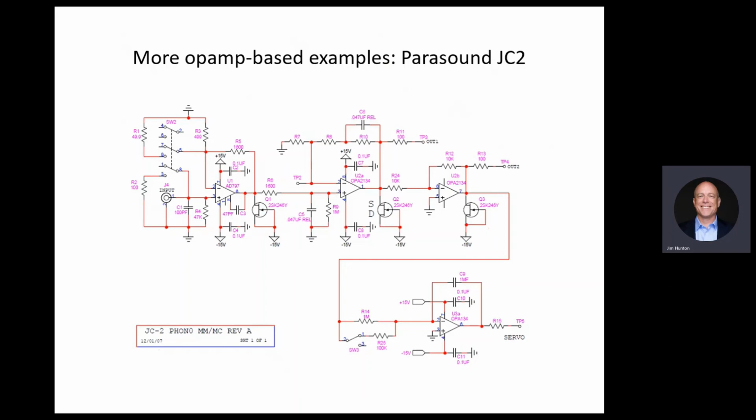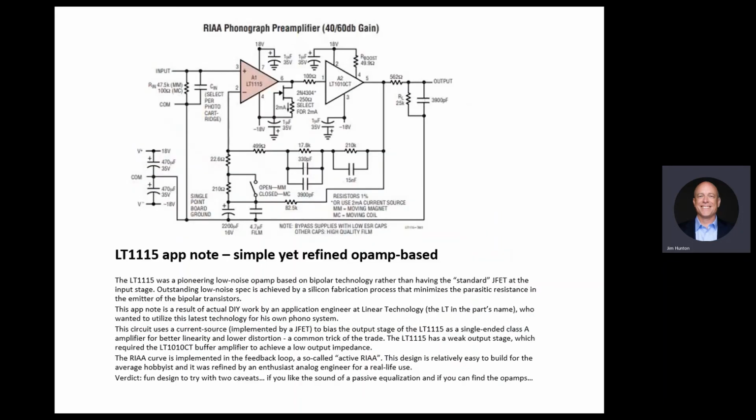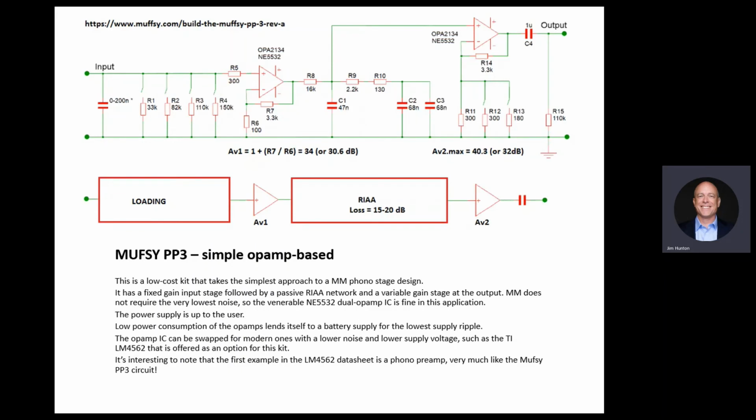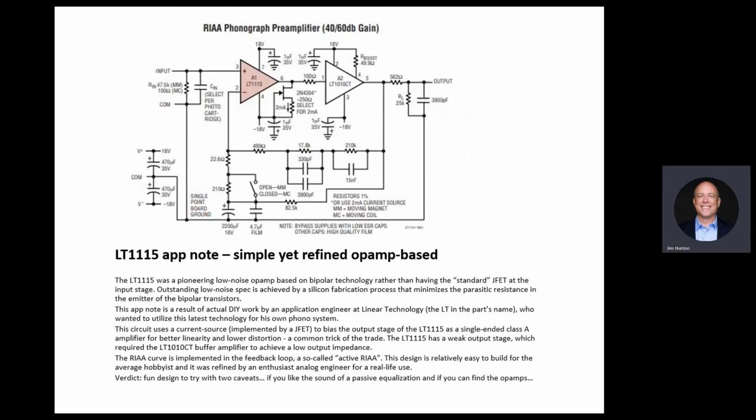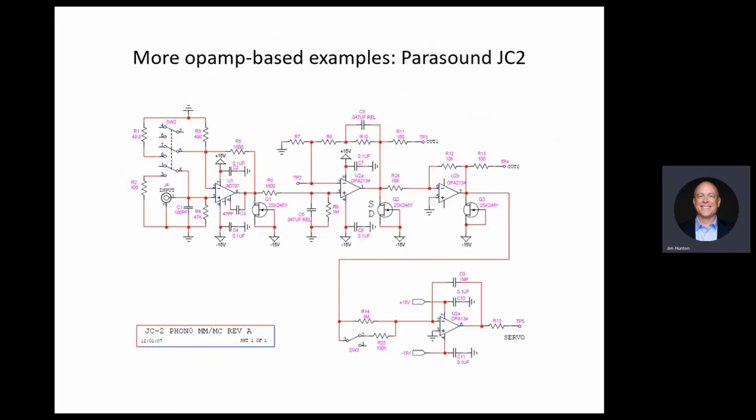If we look at the two slides before, there's a capacitor right there on the output, and this capacitor is not negligible because it's driving a preamp. So it has to be a large capacitor, and large, high quality capacitors are expensive. So we'll see another example of that.